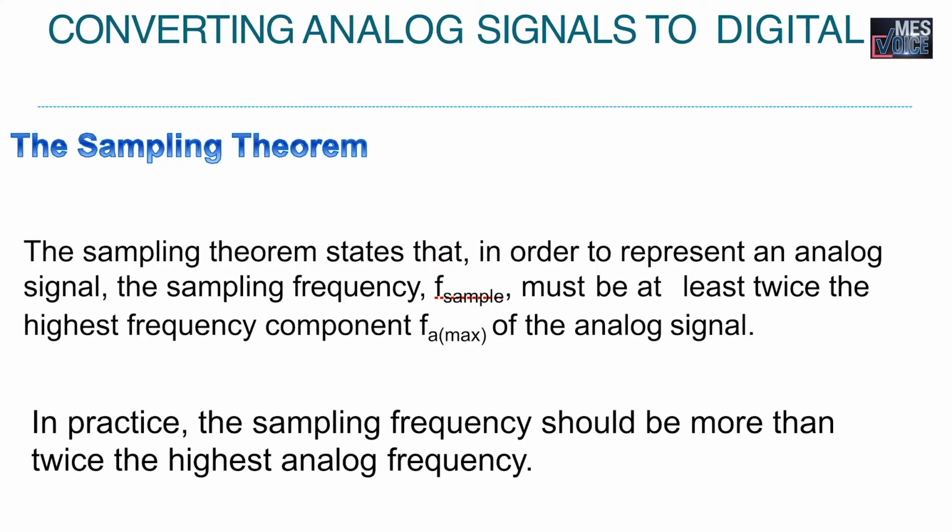The sampling theorem provides an idea about how many samples are necessary to ensure that we are preserving the information contained in the signal. If the signal contains high frequency components, we will need to sample at a high rate to avoid losing information in the signal. In general, to preserve full information in the signal, it is necessary to sample at twice the maximum frequency of the signal. This is known as the Nyquist rate. The sampling theorem states that a signal can be exactly reproduced if it is sampled at a frequency f which is greater than the maximum frequency in the signal.